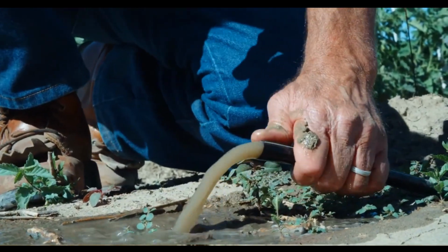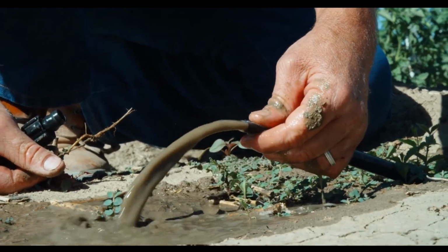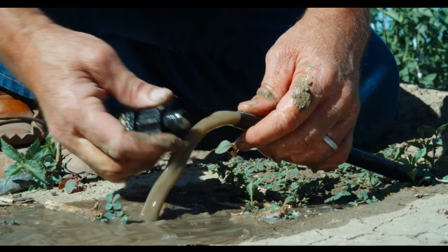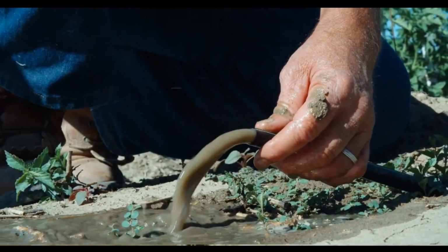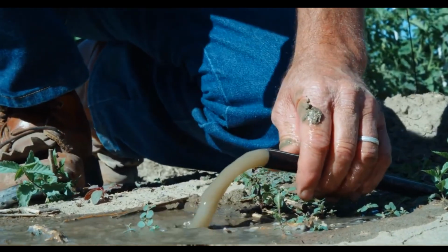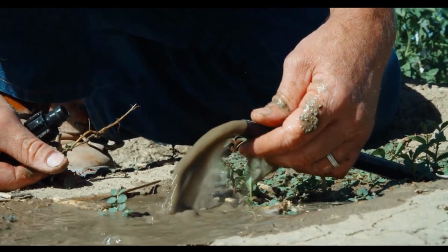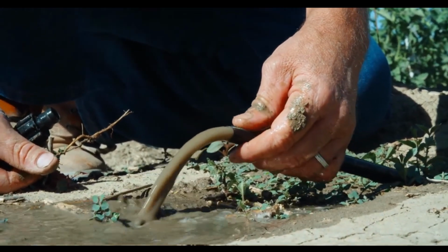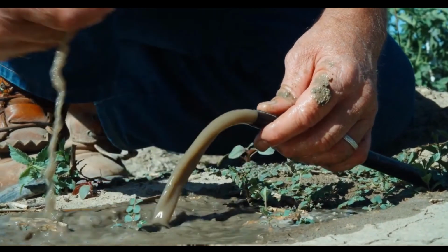And it also creates an environment for those solids to be, or for biologicals to grow, and they have a food source. And so it really impacts the life of the system. It impacts the distribution uniformity, the water use efficiency. And in fact, one of the case studies you're going to see a little bit later on, the guy was flushing his zones every single day. And that was a tremendous amount of time, effort, and water lost.